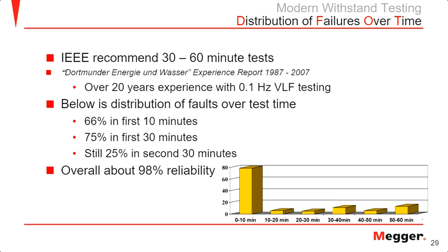If you remove that voltage, it is counterintuitive, because in the next 10 minutes, when it was supposed to fail, you have now grown that tree far enough that it might fail in service. So it is recommended, depending on the cable that you're dealing with and how critical it is, that a 60-minute test is what a lot of people go for, or a 45-minute test, which is also very normal to see in the industry when you're doing a VLF test.